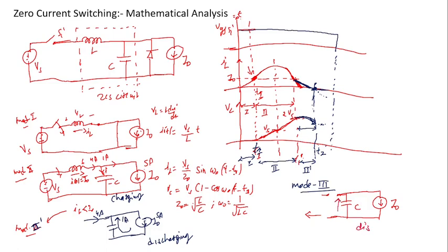So here still the capacitor is discharging in nature. So here in this mode 3, what will be happening? The capacitor will be dissipating some energy to the load, which means here the one observable point is that the inductor will be having some energy that will be dissipating through the capacitor also, and whatever the energy stored by the capacitor, that capacitor is also giving the energy to the load. So no energy is destroyed.